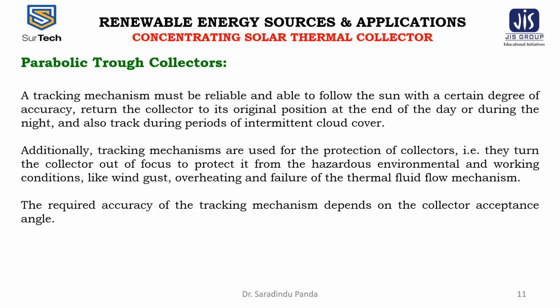Additionally, the tracking mechanisms are used for the protection of collectors such that they turn the collector out of focus to protect it from hazardous environmental and working conditions like wind gusts, overheating, and failure of the thermal fluid flow mechanism. The required accuracy of the tracking mechanism depends on the collector acceptance angle.